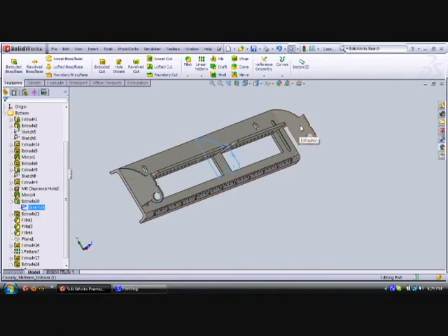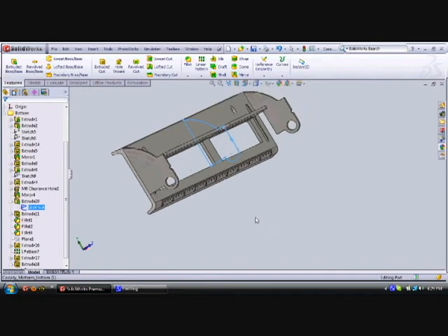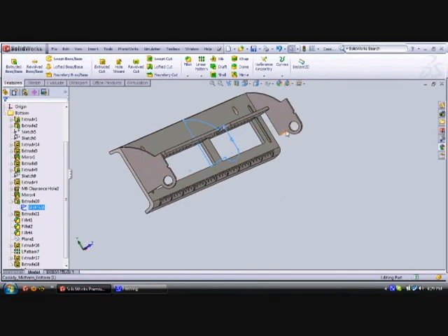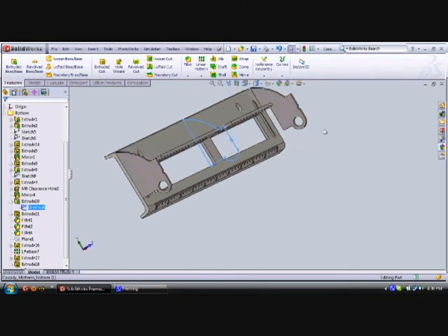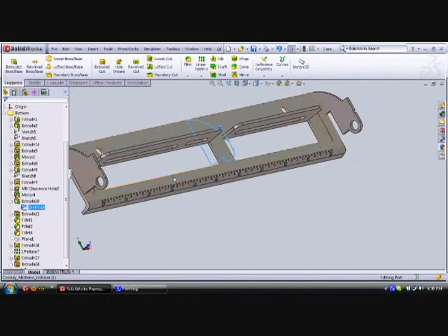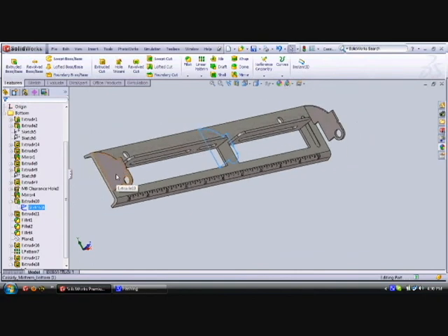I first designed this piece, this side, and then needed to design the second side. Instead of drawing a whole new sketch, I converted the arc top and the side from the old geometry and then completed the sketch. It was then self-defined, and any changes made on the right side of the bottom would then be immediately correlated to the left side of the bottom without a user having to add any extra features.